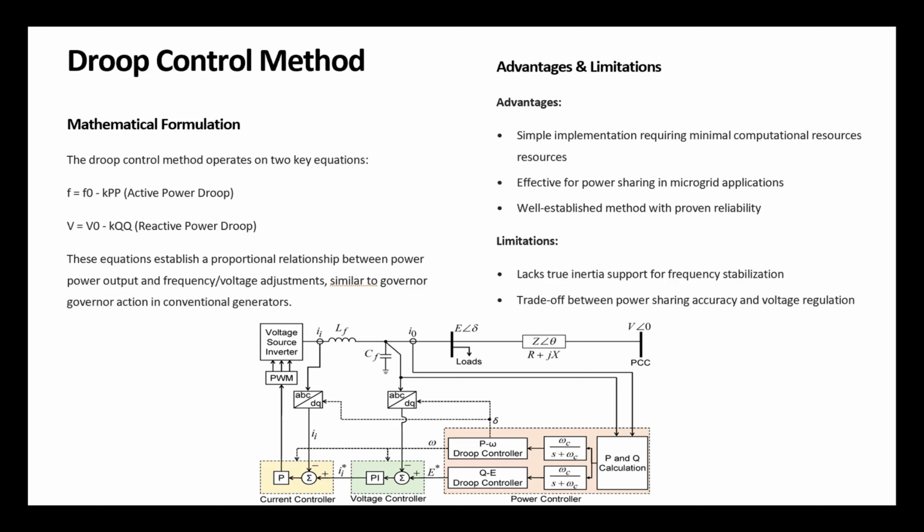But the droop control lacks the concept of inertia. Grid forming would imitate the inertia at the end of this droop control. But you don't see any concept or any parameter in your control system that represents or quantifies that virtual inertia. Meaning you don't have any observation of the virtual inertia or any leverage over it. Make sense? It is there. Droop control just can't see or quantify that.